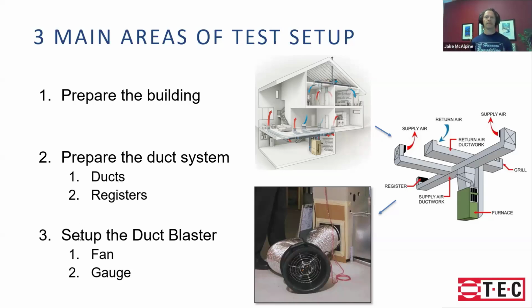And then lastly, I step down to actually setting up the equipment, and I break that kind of into two groups, connecting the fan and making sure that your gauge is set up properly so that you're ready to do your test. Okay, yeah, that makes sense. Three steps kind of at a high level. And in some ways, the analogy to blower doors helps for a newer person like me.